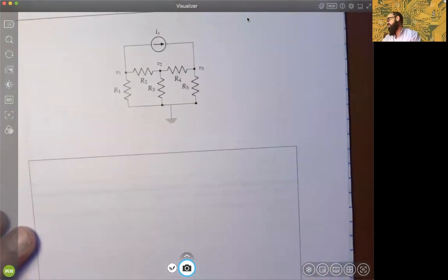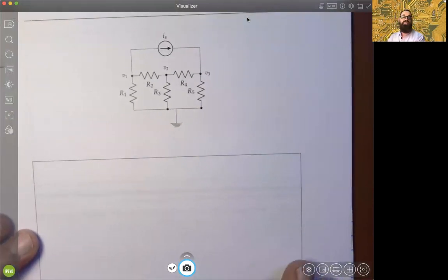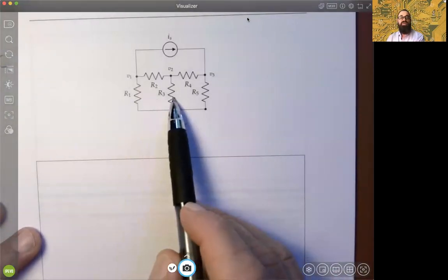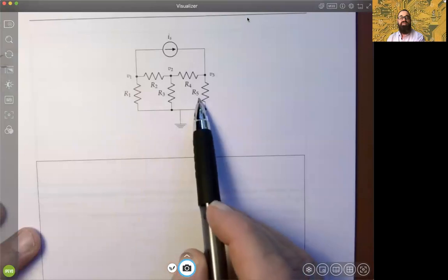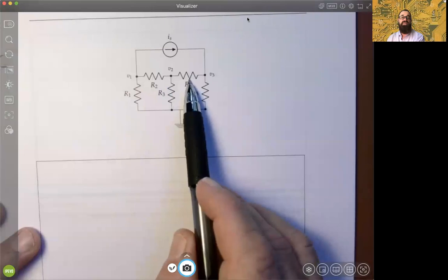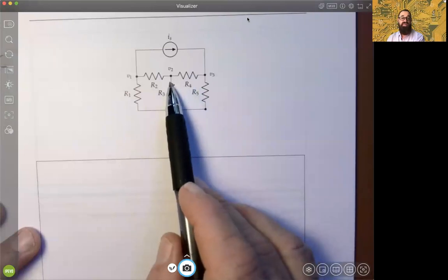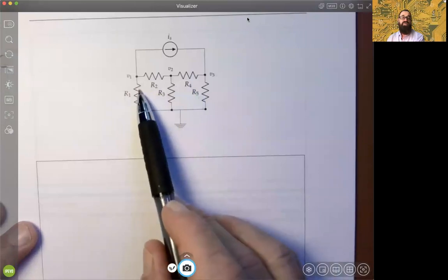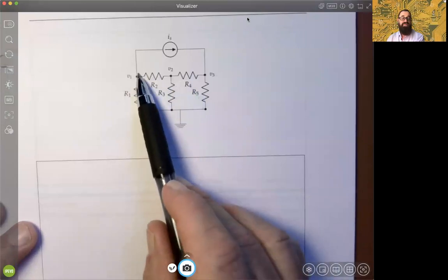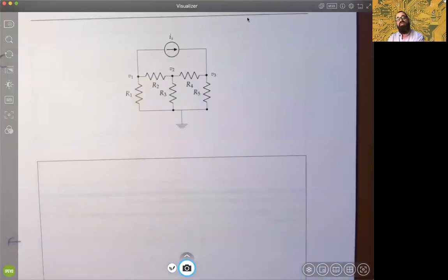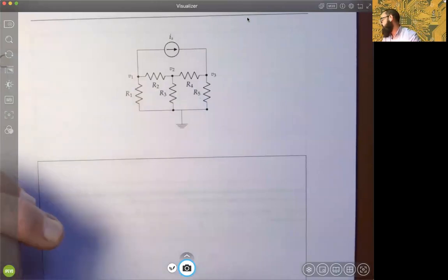this particular circuit. Again, recognizing the lack of series and parallelism here. If you look at this very carefully, R1, R3, and R5 are not in parallel because of those two resistances there. They're not in series either because of this, right? And R1 and R2 are not in series either because you have this off ramp here in the circuit. And again, it must be end to end, no other options, okay?